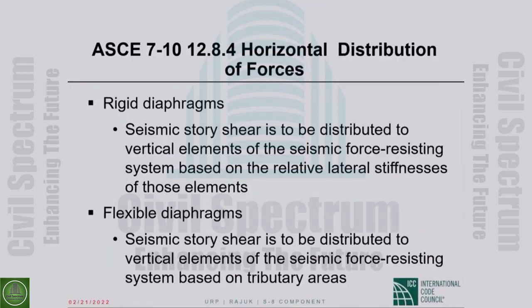This is a very important topic because, remember, we start seismic design with the design base shear. Then we do a vertical distribution of the base shear along the height, giving us the F sub x forces. From the F sub x forces, we can calculate story shears, V sub x.